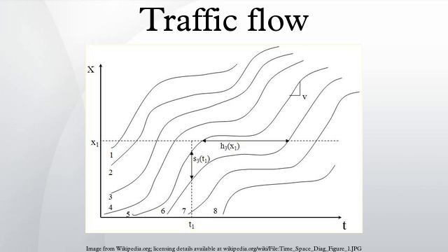Consider a stretch of highway with two lanes in one direction. Suppose that the fundamental diagram is modeled as shown here. The highway has a peak capacity of Q vehicles per hour, corresponding to a density of kc vehicles per mile. The highway normally becomes jammed at kj vehicles per mile. Before capacity is reached, traffic may flow at A vehicles per hour, or a higher B vehicles per hour. In either case, the speed of vehicles is Vf, or free flow, because the roadway is under capacity.